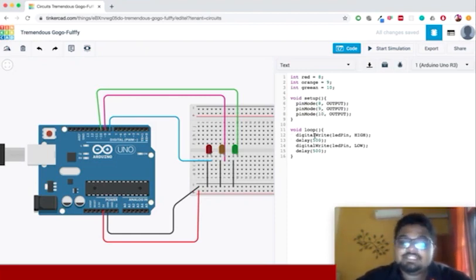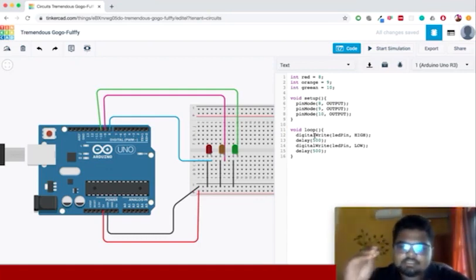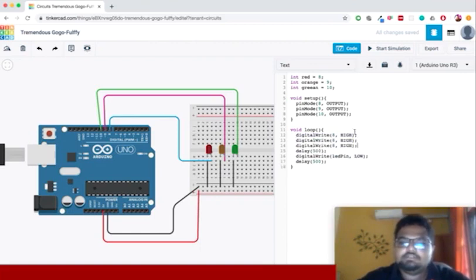And now to blink the entire traffic light off and on, I will say 8 high, at the same time the other 2, 9 and 10, also high, and for the low, 8 will be low, that is to switch off the red LED.